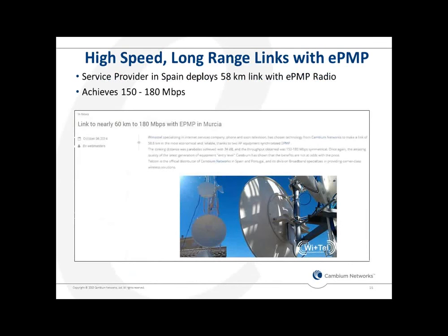We have a lot of people out there using the ePMP in point-to-point mode. Here's a very interesting case. Recently we had a service provider in Spain who deployed what I think might be the longest ePMP link out there. They used a very large dish. This is not a Force dish. This is probably a 3-foot dish here. It's a 34 dBi dish, and they were able to achieve 58 kilometers with their ePMP radio and 150 to 180 megabits per second of throughput.